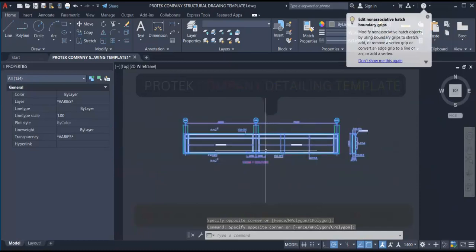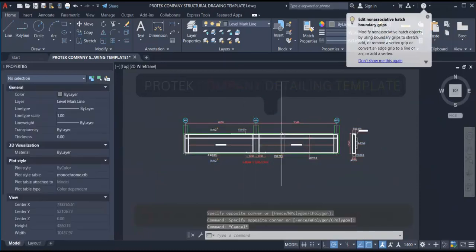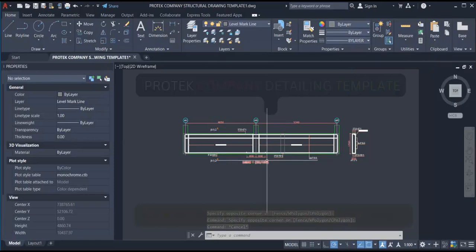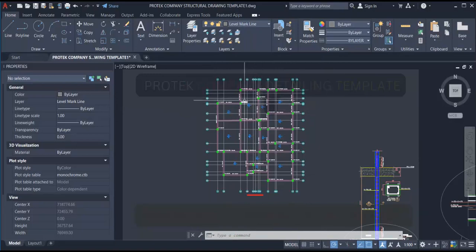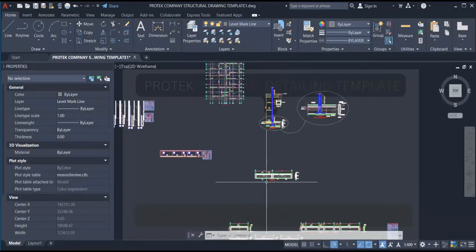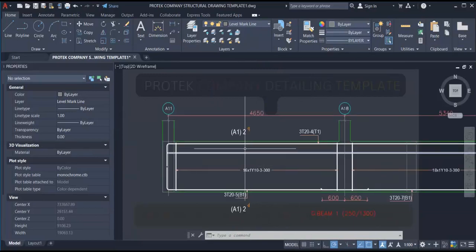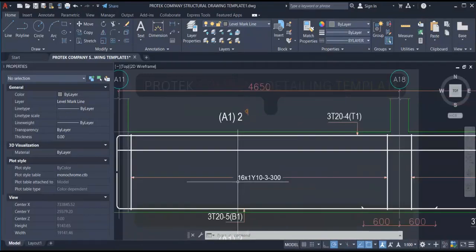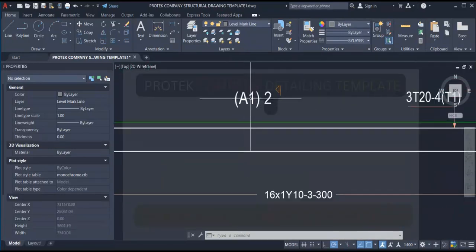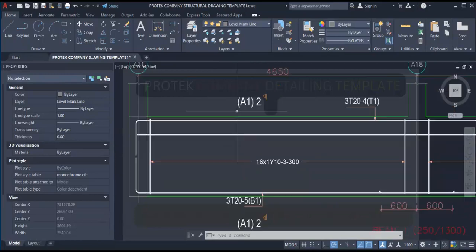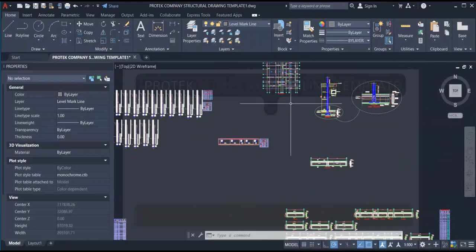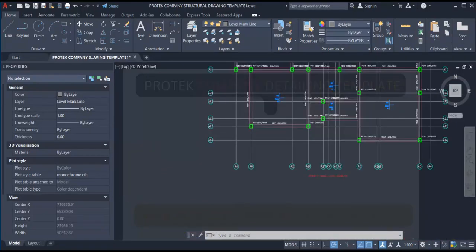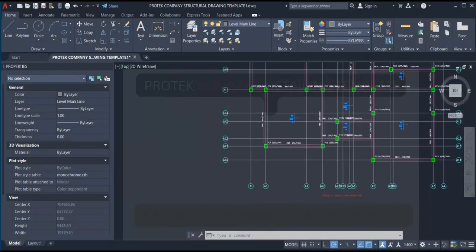Over here, I have a ground beam layout. This is my ground beam layout. For me to identify this beam on the ground beam layout, I will have to check the axis in which this beam lies. This beam lies along the axis A1, so I'll have to look for a green line A1 to be able to find this beam. If I go to the ground beam layout and check, see, this is the green line A1, and the beam is on the green line.